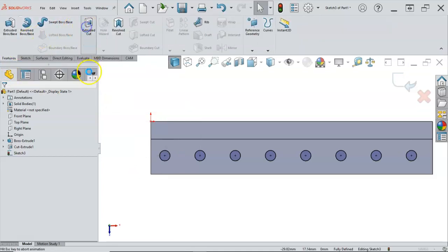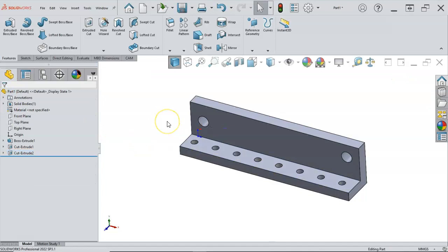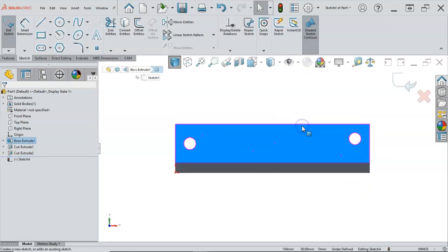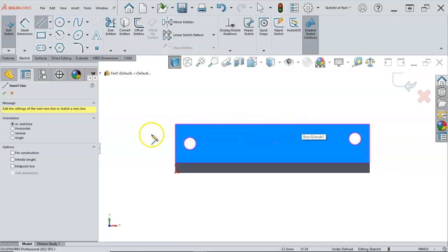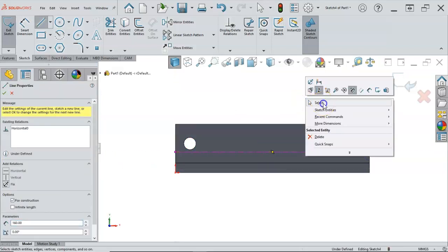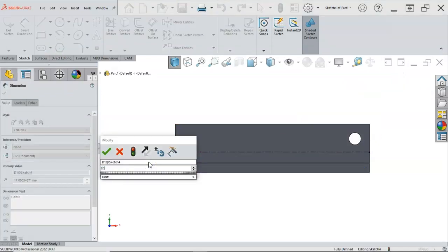But we'll go into the extrude cut. It's already set up to next because that's what I used last time. We go ahead and accept it, and you can pick whatever name you want to put on. Last time I just rough positioned the sketch. If I want to control that a little bit more, then I'm going to go into line, make it for construction. And if I want this text to be centered, I'm just going edge to edge. And we'll go 20 millimeters.